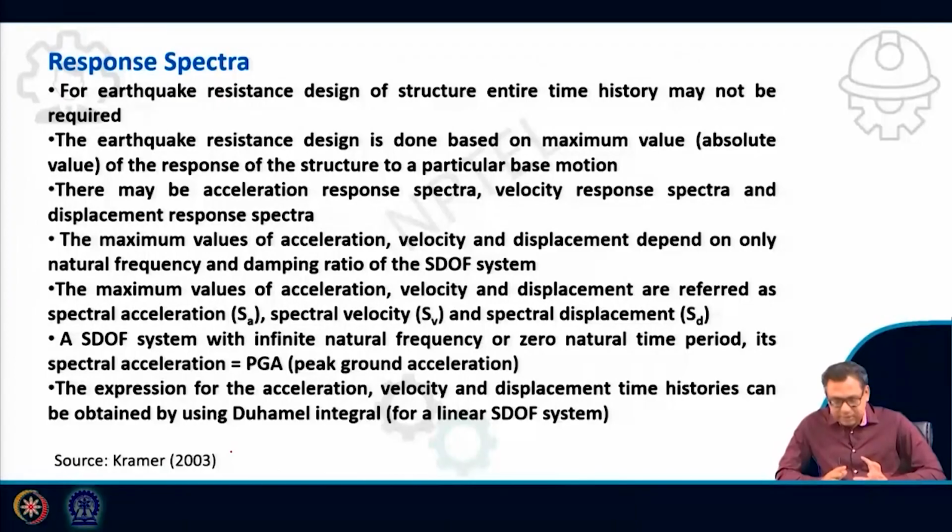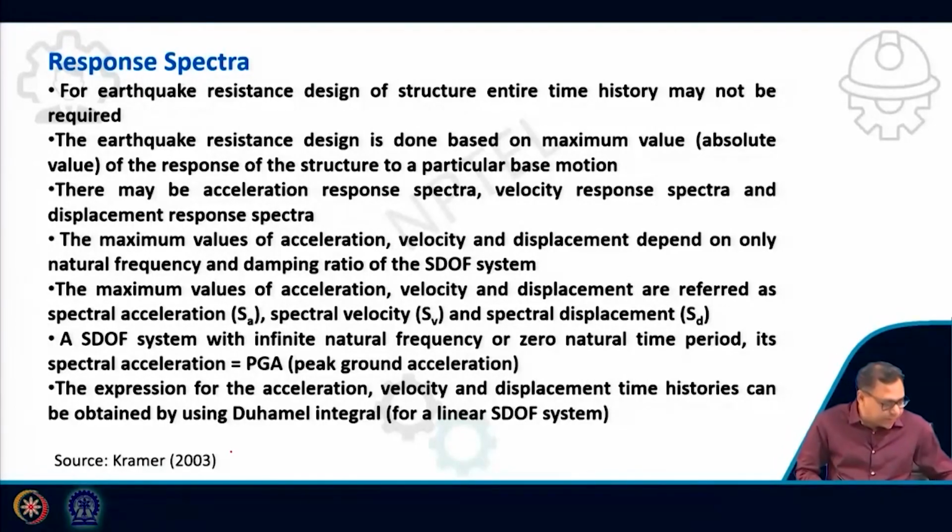So that means you will get the expressions for displacement, velocity and acceleration. From there you will get the maximum values of displacement, acceleration and velocity, and you plot them for different time periods, then you will get the response spectrum.